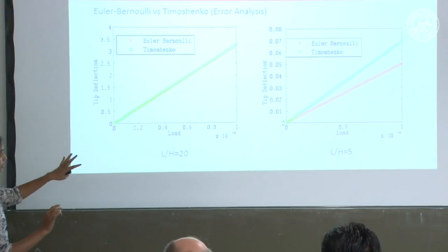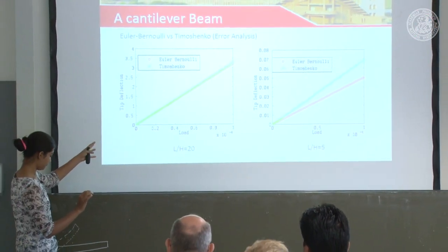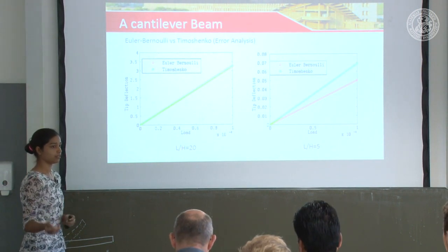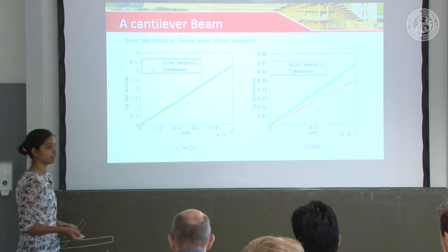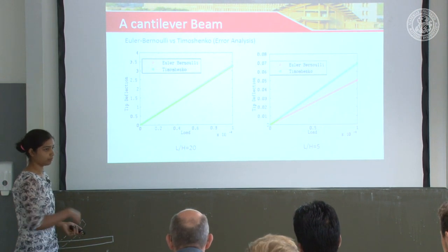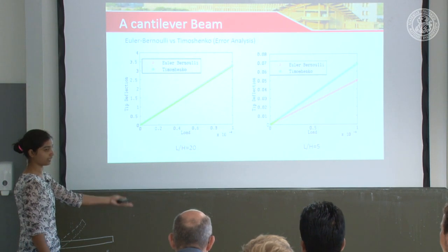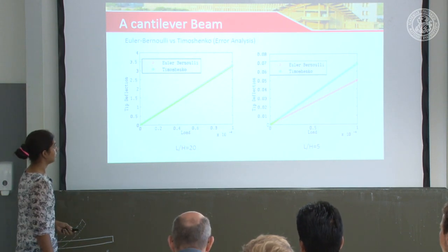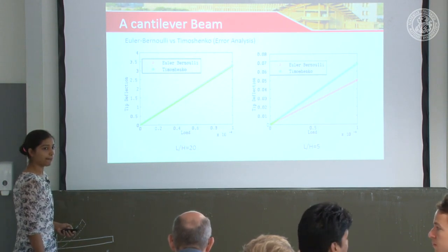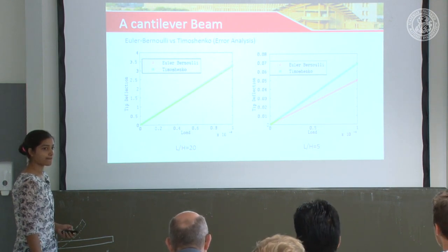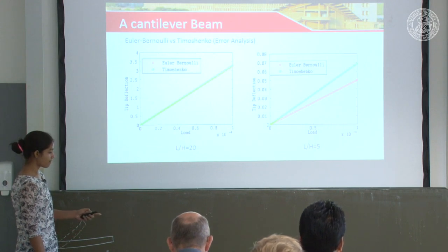This shows where to use Euler-Bernoulli beam theory and where to use Timoshenko based on the geometry of the rod. We can easily find that out using that little formula. You can also say that shorter or longer is a relative term and it is related to the right hand side over there.